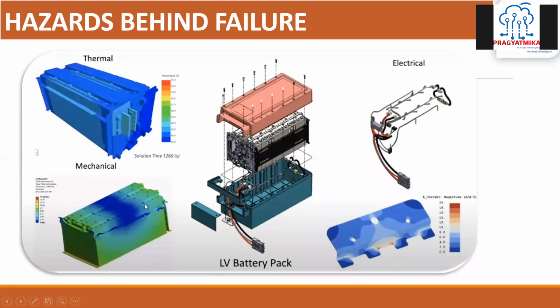Thereafter, the wires or connectors you are using, the sensors you are using for the temperature measurement, the length of them. Thereafter, the BMS you are using with your battery pack. The BMS has wires going to sense the voltage of the cells, so the length of those wires also needs to be taken care of, and there are proper calculations which ensure that similar balancing within the cells should happen.